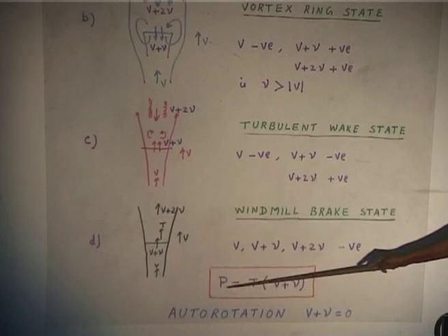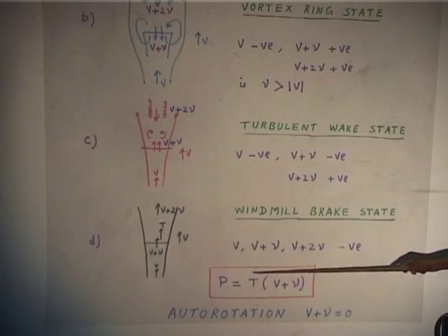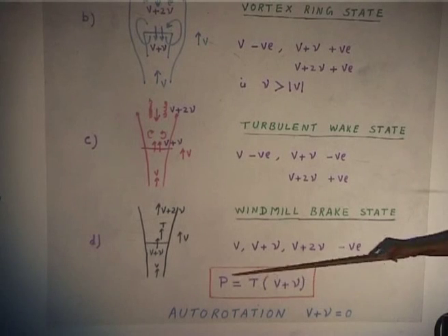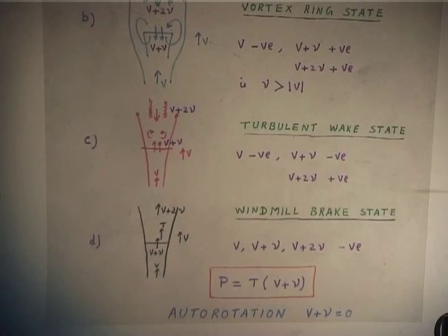This is the induced and climb, the power required for climbing and induced. When that power is 0, that is called auto rotation. But actually you will find in real situations auto rotation is a little different, that we will learn, because this you have to know. That means I do not require power to support my weight, but that does not mean that I am hovering, please understand, I am coming down.